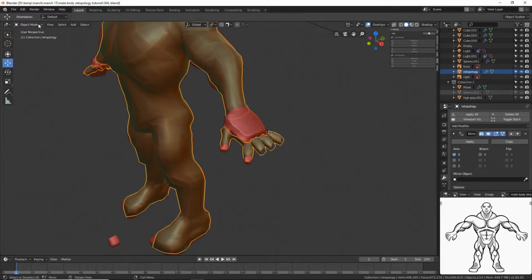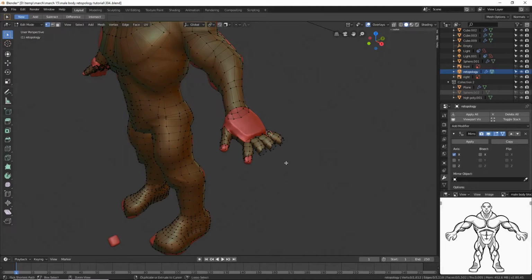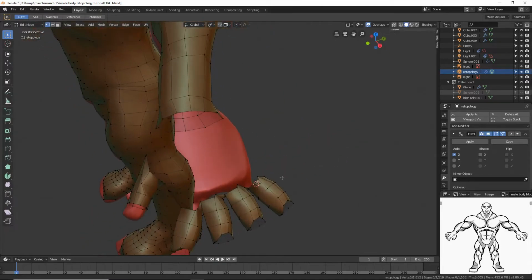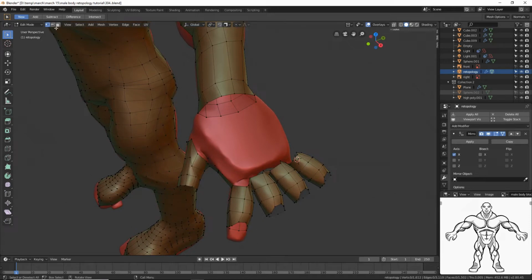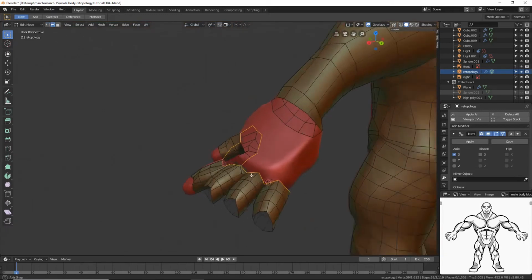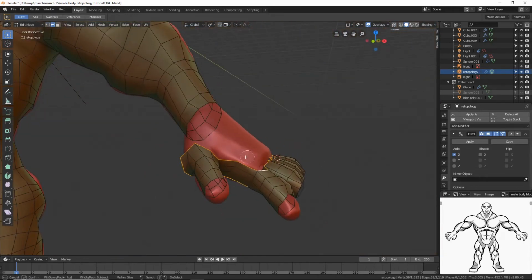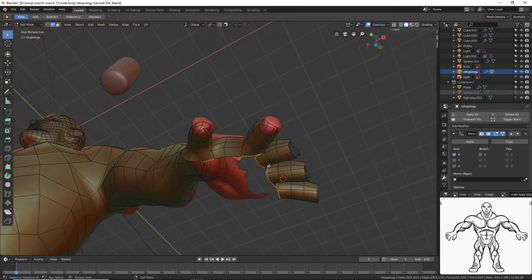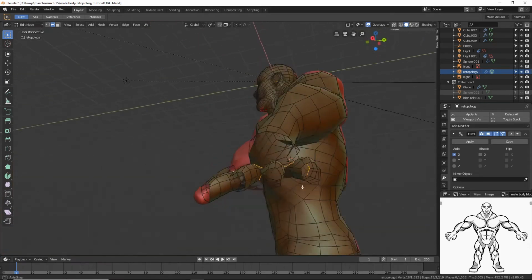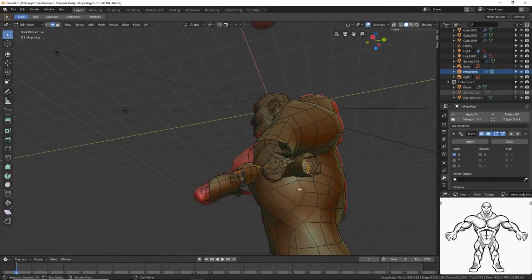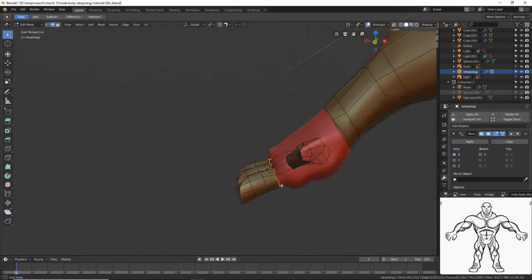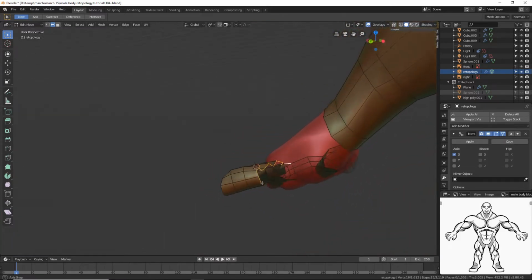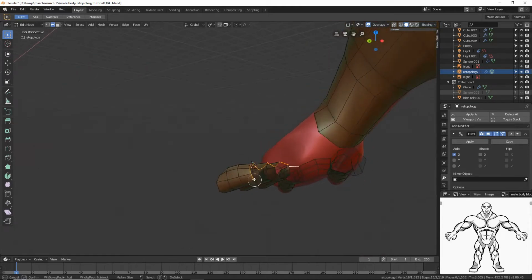Now I'm going to go to the upper left, go to edit mode, hold control, zoom in. I'm going to go to edge select, hold alt, left click. So I selected that top edge there. I'm going to press C to deselect that bottom edge pieces that I don't want. Just want the top. This as well here. Press C.